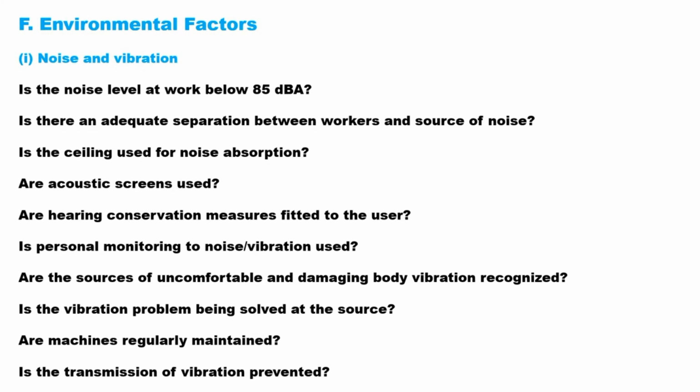F. Environmental factors. I. Noise and vibration. Is the noise level at work below 85 dBA? Is there an adequate separation between workers and source of noise? Is the ceiling used for noise absorption? Are acoustic screens used? Are hearing conservation measures fitted to the user?